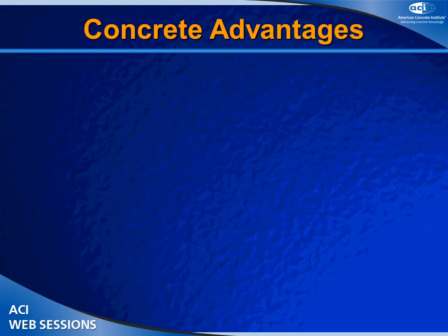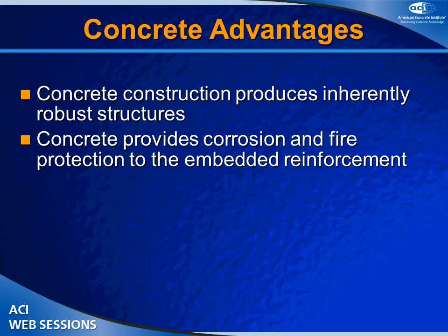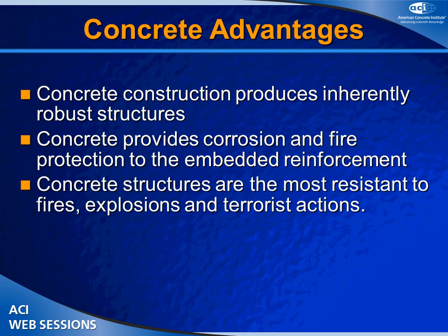Concrete has a comparative advantage in robustness. You look at the thickness and the stiffness of concrete versus steel. That's a big plus. Concrete automatically provides corrosion resistance and fire protection to the tank structure. And it's more resistant to fire and explosions. Terrorist actions have been a consideration, and it's not just after 9/11. This was, to some extent, a consideration earlier on.